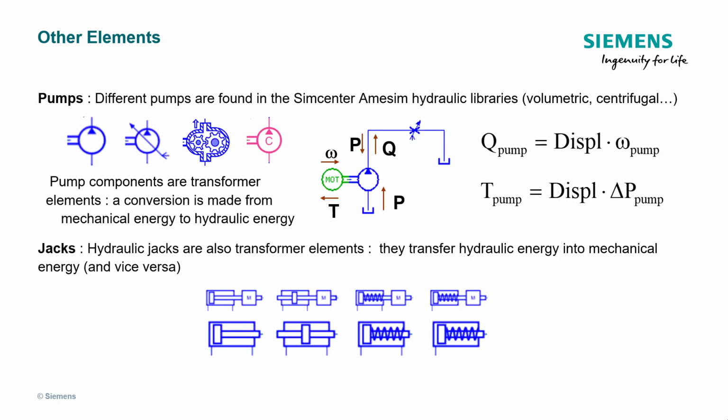Different pumps are found in the SimCenter MSIM hydraulic libraries, such as volumetric, centrifugal, gear pump, etc. Pump components are transformer elements. A conversion is made from mechanical energy to hydraulic energy. Hydraulic jacks are also transformer elements. They can transfer hydraulic energy into mechanical energy, and vice versa.